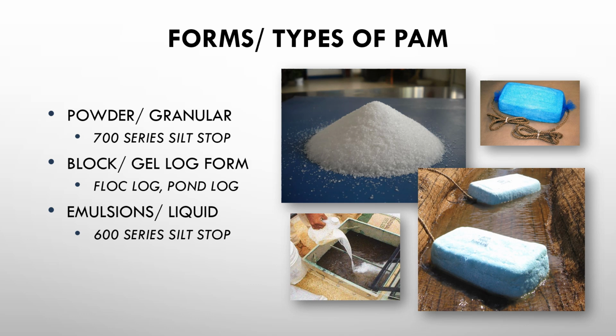There are other people that use liquid emulsions for water treatment. We've spent quite a bit of time already talking about how PAM has low toxicity and is safe for aquatic organisms. Now, with the liquid emulsion forms, the PAM is safe, but the surfactants and the emulsifiers they use in those liquid emulsions can carry some toxicity.